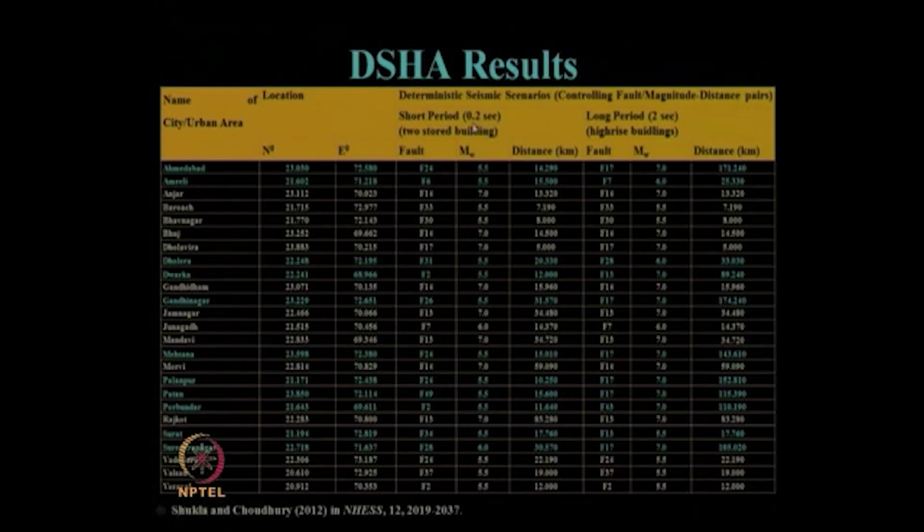N by 10 is the formula which as a thumb rule we use to obtain the natural period of any structure. So, if it is a 2-storied building, then it comes to about 0.2 seconds, which is considered as a short period, whereas the long period we considered in the present study is 2 seconds, which is about how many storied building? A 20-storied building, right, as per our thumb rule typically, remember.